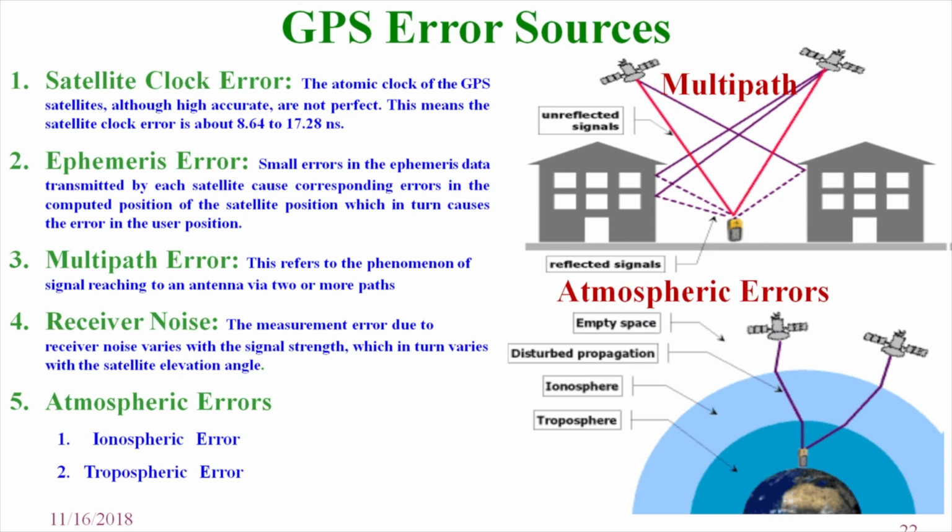But there is an error. There is also an interference error. This error arises due to the small error of the transmitted satellite. So, there is the location and computation of the position. Sometimes there is an error in the computation of the position, and sometimes multipath error.